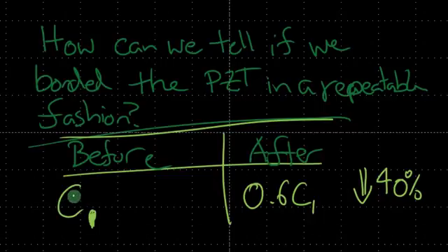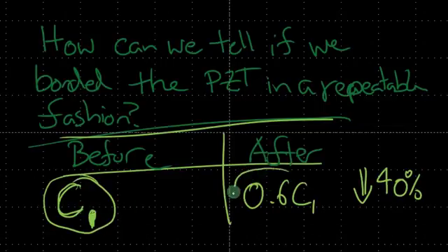And anyway, you should first identify those piezoelectric components which have the same capacitance. And then what you should do is see how much they change when I bond them. And if they're all changing the same amount, you can be sure, in all likelihood, that each of them are bonded in very similar ways, and therefore you should have a repeatable result between them.